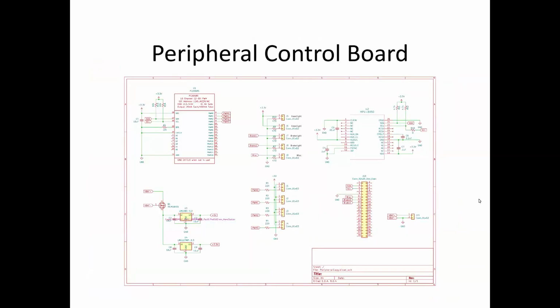The main system is controlled by an MPU 6050 accelerometer and gyroscope, which has been designed around the manufacturer specification to be able to interface directly with the Raspberry Pi using the I2C interface. There's also a 40-pin connector to allow everything to mesh over perfectly with the Pi. And to control the outputs with the servos, it's a PCA 9685 PWM driver, of which we're using 4 of the outputs to be able to control our 4 servos, with 2 for each wing.